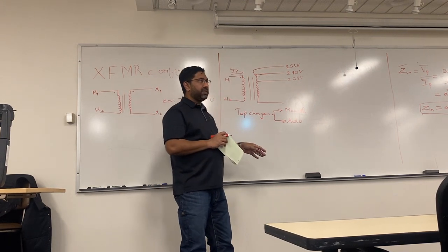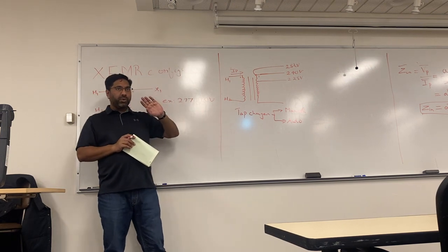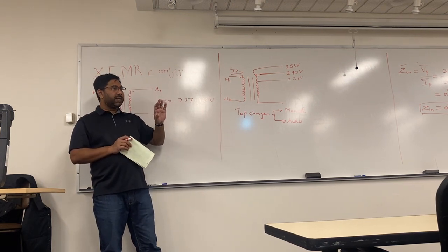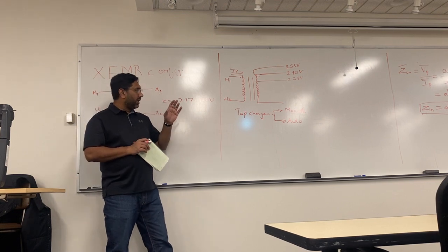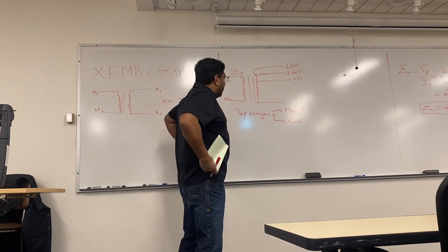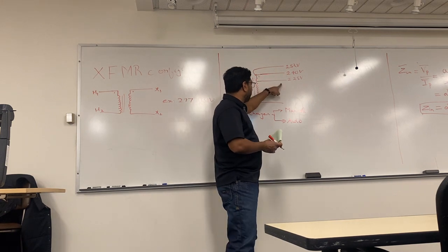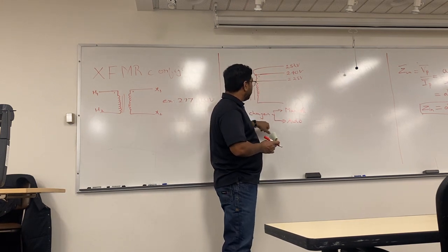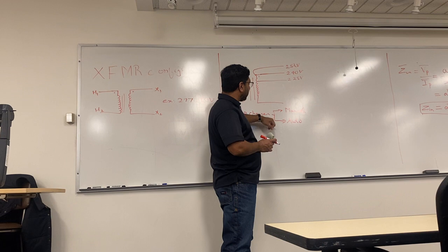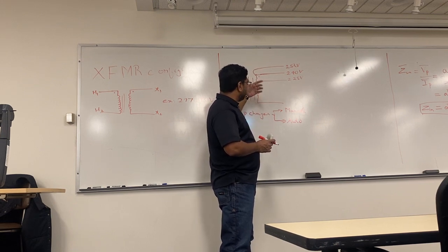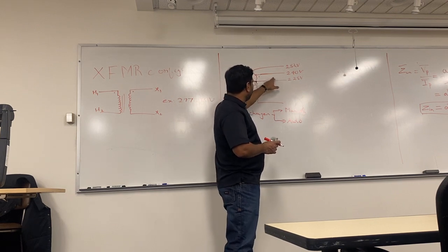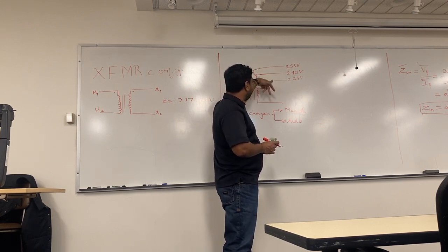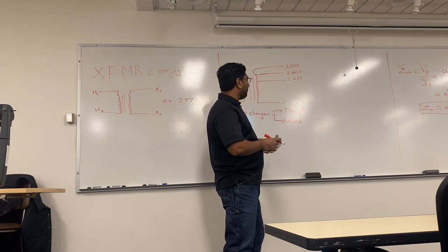What that means is, imagine rural America, you know that at a certain time, farmers are going to switch on their pumps and whatnot, and they would rather have a higher voltage than a lower voltage, and the tap changer just knows at a certain time of day to go up, and during night just to come down. So essentially you would be sticking it at 240, but every now and then you have to tap up or tap down. 5% is what I've seen.